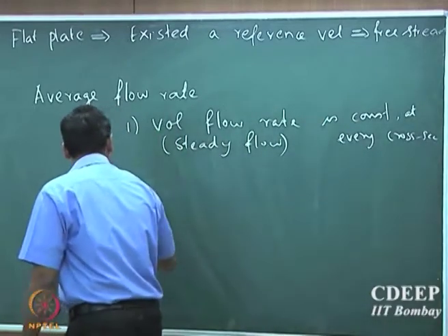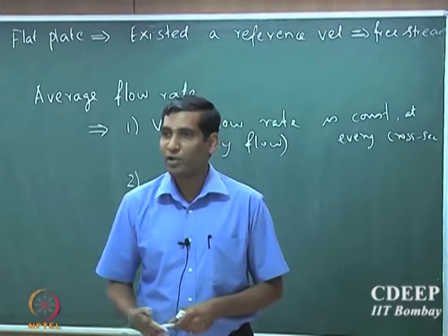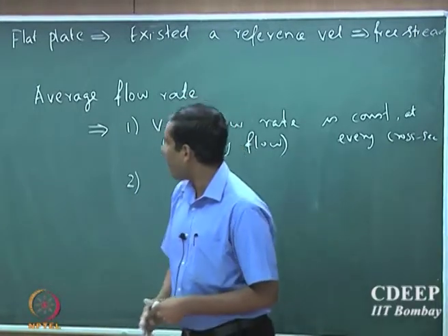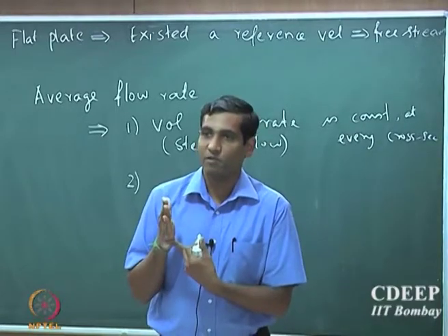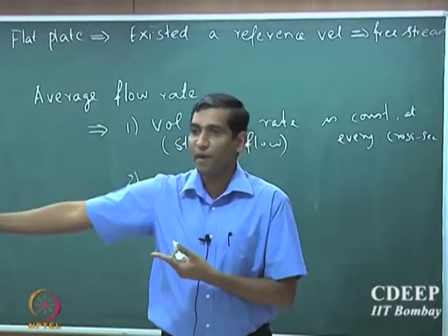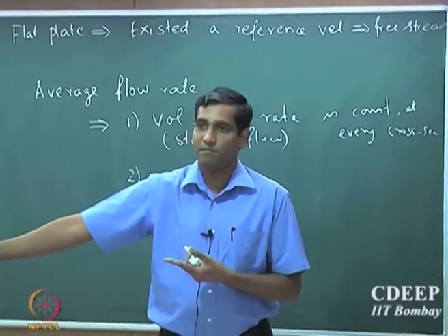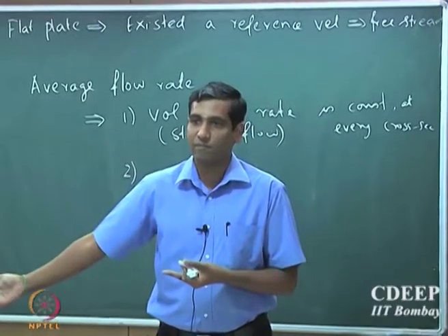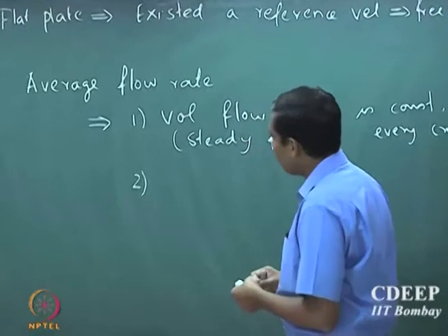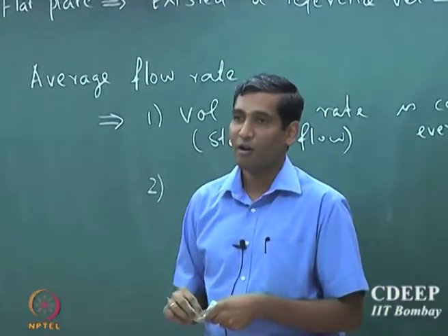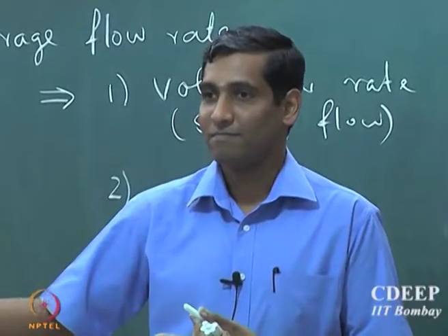But much more important than that, if I put a flow measuring device at the end of the pipe, let's say a rotameter, or some other meter, or a venturi meter, for example, what I would measure is actually the average flow rate.